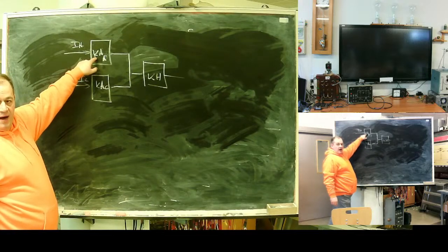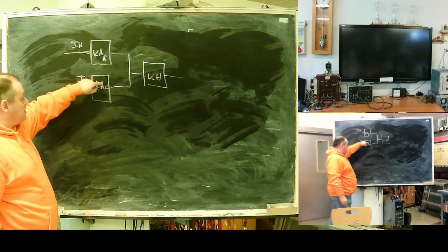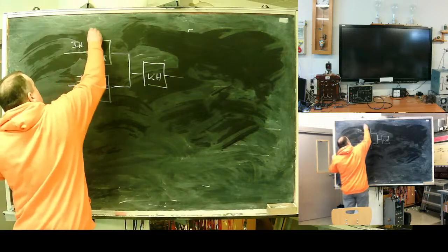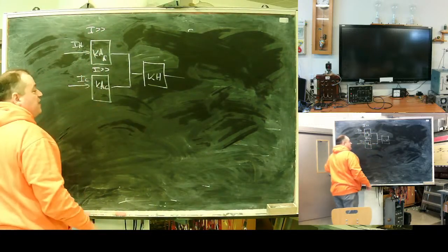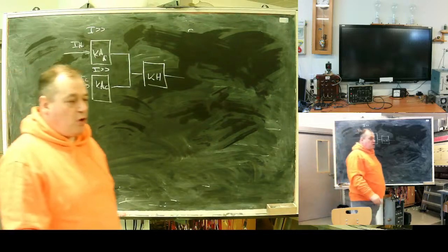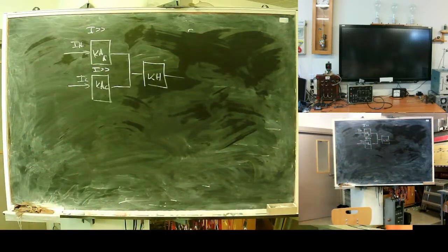Relay, A, amperes. So these are 2 overcurrent relays for phase A and C. This box is intended for a network with isolated neutral.